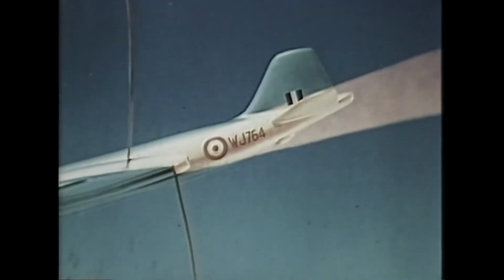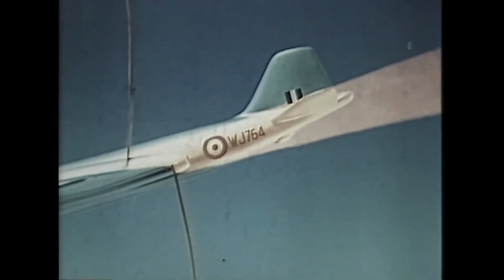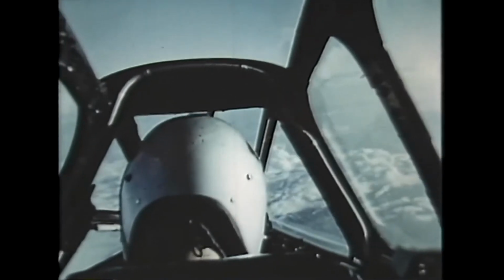The turbulent airflow from behind the shock waves may hit the tailplane or other parts of the aircraft and cause buffeting. Or the controls may be affected. Here, slowed up about 40 times, is a Schlieren picture of what may happen to an aileron as a result of shock waves.